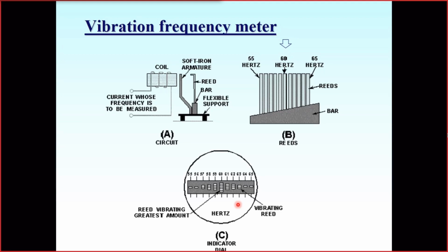From the illustration, you may easily understand which country the frequency meter was designed for. It's certainly designed for the United States, because the United States has a 60 hertz standard. So this meter is designed to show frequency from 55 to 65 hertz. These meters were not very wide-ranged, because the main application of such meters was control of the frequency at the power station.